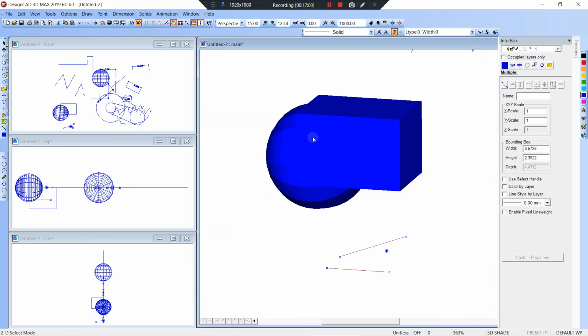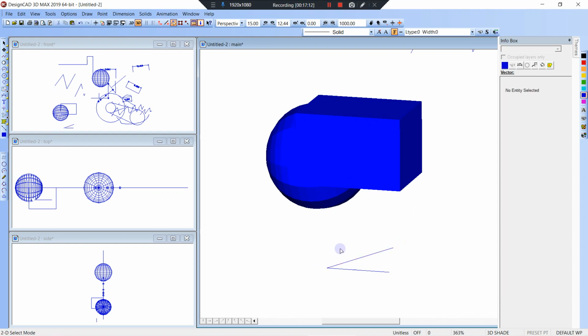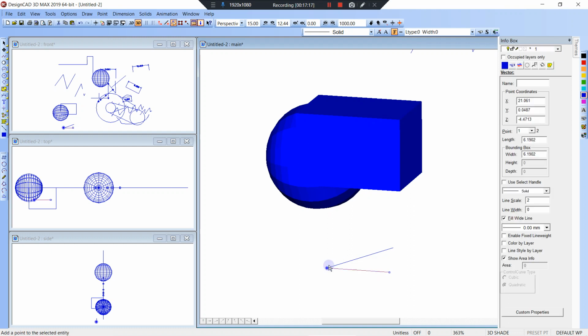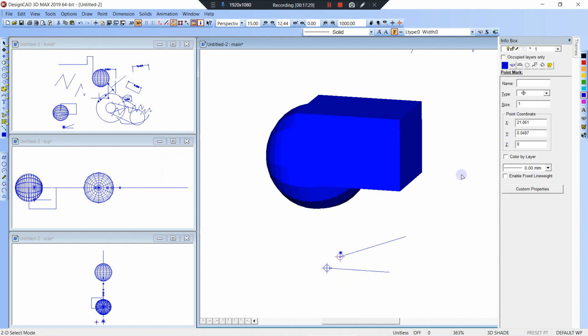It was hard to see that. Now I can take that. See, it's funny because it's 2D, but they were in two different planes. Because when you're drawing on 2D, it's going to be always at 0. And this, can just show you. So this, if we draw a point on this one and this one, and then we highlight this one was the one we drew in 2D, it's going to be on 0 elevation. This one we drew it in 3D, it was at different than 0 elevation. So when I drew it, it was hidden behind this one.